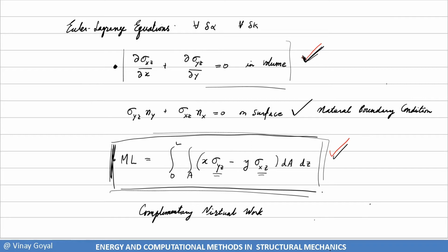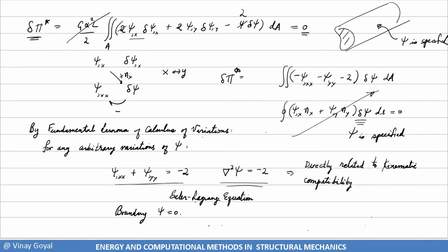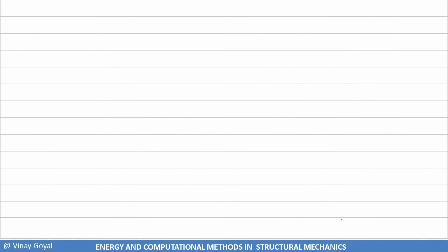And so I would like to look at that again, because I don't think we have substituted the Prandtl stress function here to see what will happen. So let's do that so you can see what happens there. Because right now we satisfy the Euler Lagrange equation. That's your Euler Lagrange equation. I write it here. But I haven't talked about the moment, what to do with that moment. So let's look at that moment calculation.